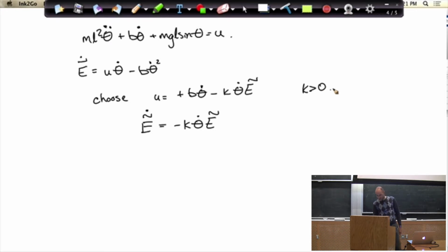If you want to make this dynamics true, even though you had some damping in the original system, then that same recipe tells you to run the same controller I did with the undamped system, but also actively cancel out the damping in the system. So apply some torque that counters the damping torque in the system.